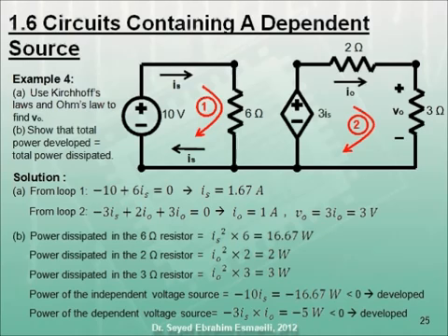Looking at this circuit, we find that there are two closed paths, the one on the left with current Is and the one on the right with current I0. In order to find V0, we need to find I0, since V0 equals 3I0.